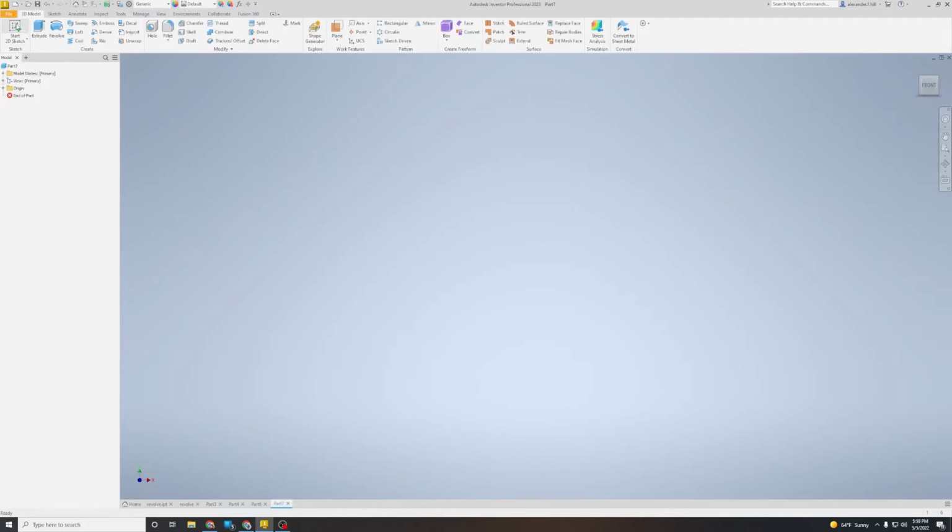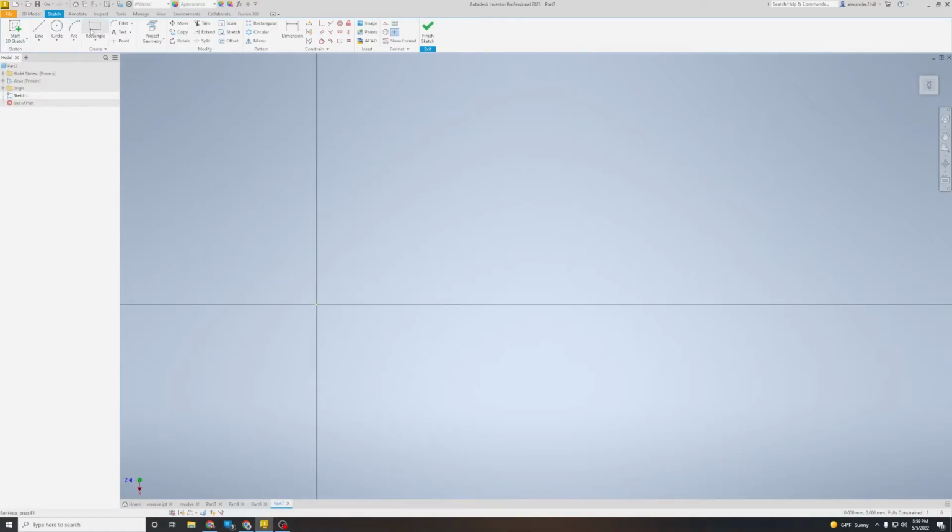I'm going to start my sketch by clicking Start 2D Sketch and choosing my plane. I'm going to use the rectangle tool, and I'm going to draw one out that is 12 millimeters tall by 15 millimeters wide. Looks a little square. I'm going to adjust my 12. I'm going to hit the escape key to leave the rectangle tool and double click my 12 and change it to 6. Remember, this is going to be doubled to the other side as it's revolved around.